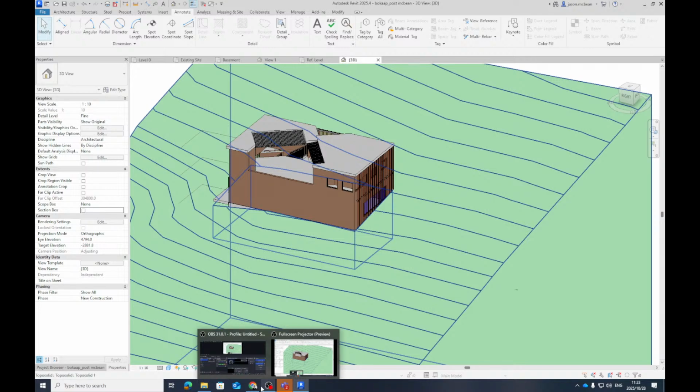Technically, where's your site boundary? Is your site boundary here? Yeah, it's this line. Technically, everything should be on your site. Sometimes they call this a servitude, where both properties will have a servitude. You can't build over the servitude, technically. But you share the servitude, and it's on your property. Anyway, very basic, you're going to start with a rodding eye, where they get access. That will continue.